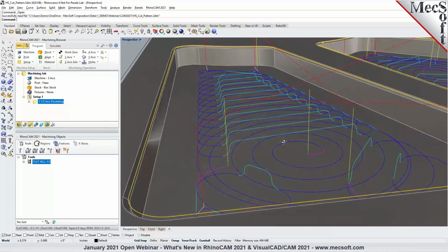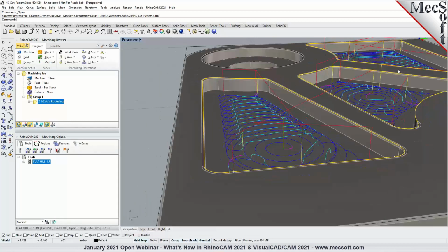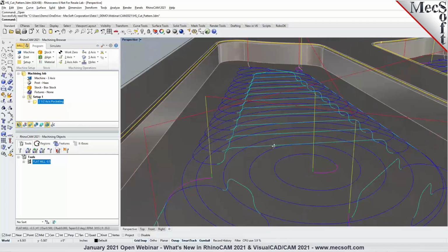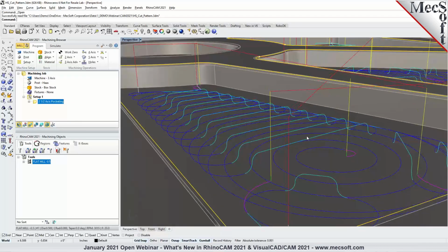Yeah, this was an enhancement some of you had requested because that was actually leaving tool marks on the part as the cut traverses from one tangential arc to the other. It would actually drag the cutter along the already cut surface, and that would leave tool marks. So this one would take care of that. Thank you. And this enhancement is included starting with standard configuration and up. So standard, expert, pro, and premium, all of the configurations mentioned will include this enhancement for the cut lift.